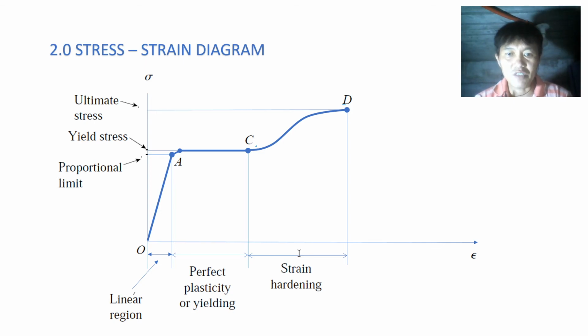Elongation of the test specimen in this region requires an increase in the tensile load, and therefore the stress-strain diagram has a positive slope from C to D. The load eventually reaches its maximum value, and the corresponding stress at point D is called the ultimate stress. When a test specimen is stretched, lateral contraction occurs. The resulting decrease in cross-sectional area is too small to have a noticeable effect on the calculated values of the stress up to point C.